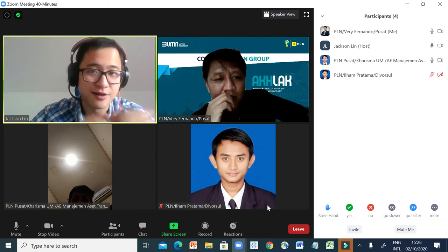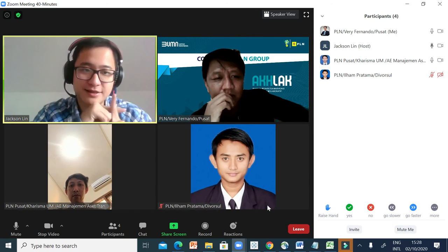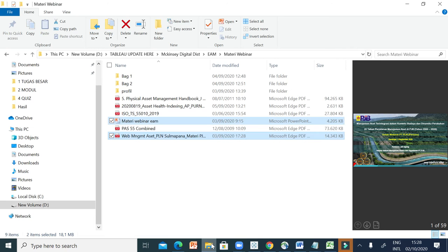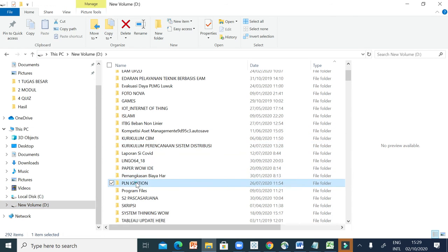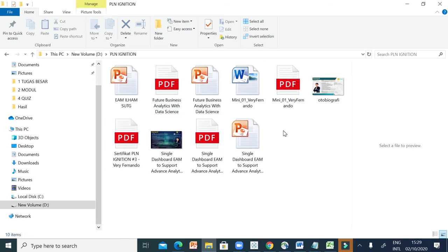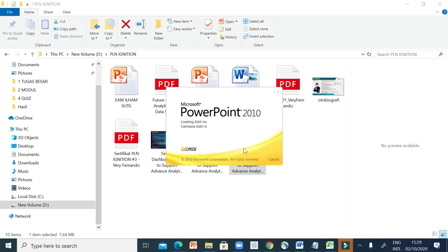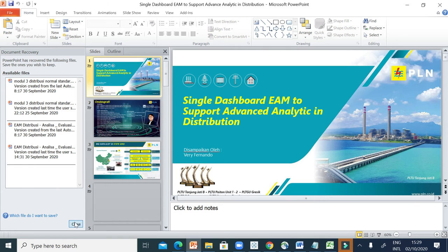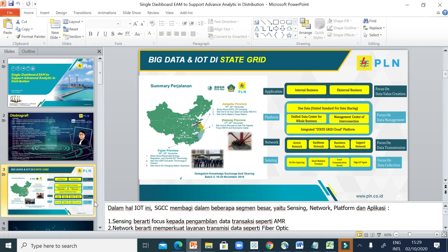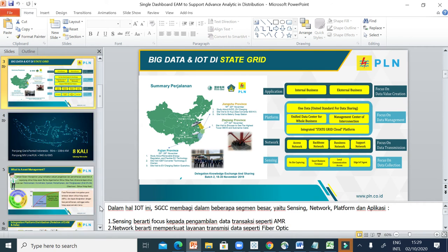We will need the data to be collected in one place, and then this amount of data is used for analysis. We don't analyze just one equipment, we analyze the entire network, so many equipments and many tags together. So the first step is to set up this centralized data, which we could call a data historian.